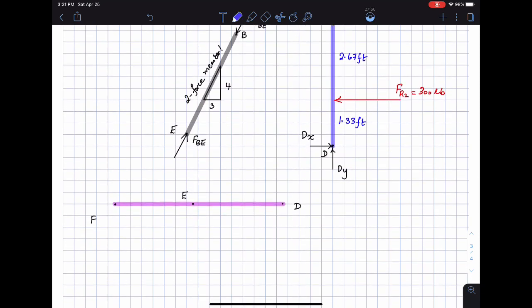And if you look at the forces, first of all, at the pin at F, I had forces Fx and Fy. Okay, if you recall, this was the force Fx, and this was the force Fy. Right? This was force Fy, and then at pin E, I'm going to have FBE, which is going to be equal and opposite to whatever I had here. Okay, so if I just duplicate that and bring that here, that's going to be FBE, and I have the slope triangle which is given to me, which means that at the pin at E, I can break FBE into its components.